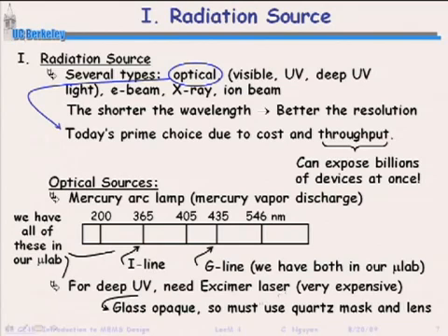Okay, but there is a limit to wavelength, right? There's a theory behind this, and so how could people beat the theory? Well, there are different tricks that people have been playing, right? Some of it's in the mask. They're now using masks that are phase-shifting masks. And phase-shifting masks can actually improve the resolution versus what you thought you had before, but it takes a little more energy, work to create that mask now. So the mask cost starts rising as we get to these finer and finer feature sizes.